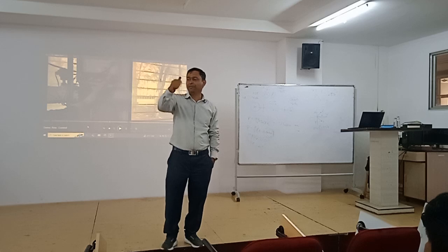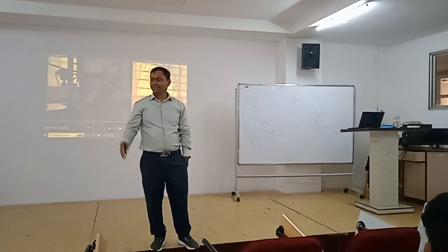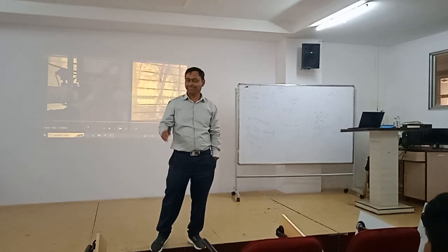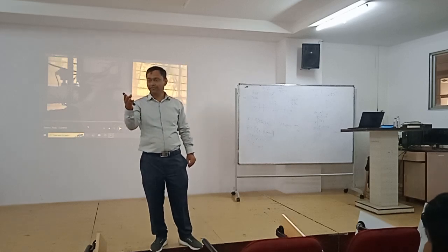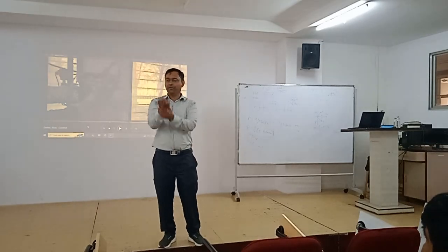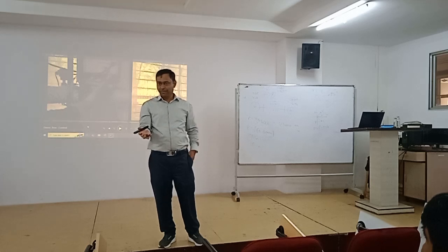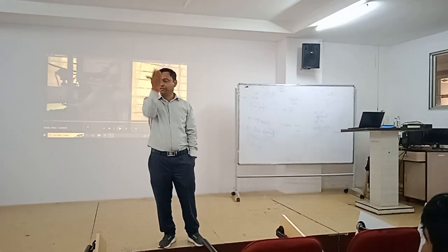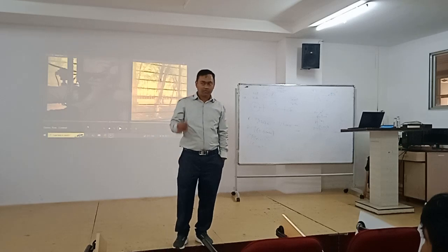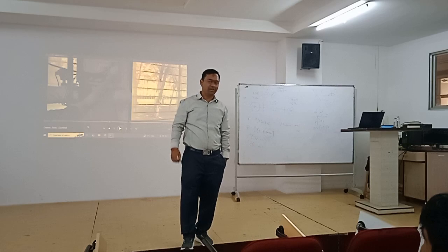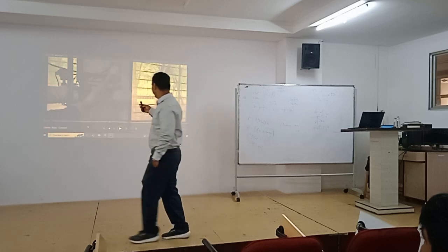How can the difference be nullified? By increasing control effort. So what is the meaning of increasing control effort? In this case, motor will start taking more current. The motor speed will increase. Obviously, if you are having less flow, to increase the flow you need to increase the motor speed only. How much will it increase? It will reach the maximum speed. Correct?